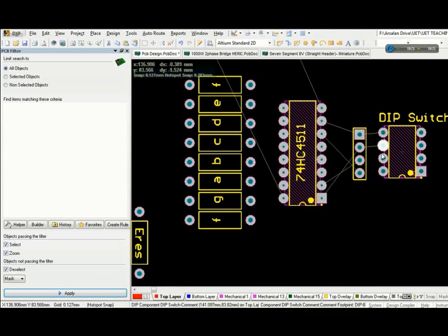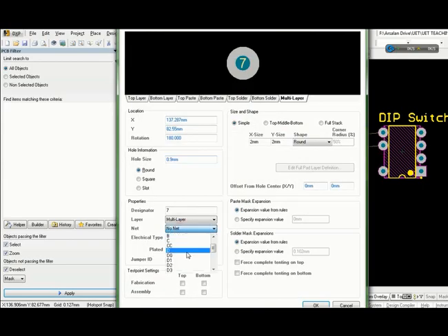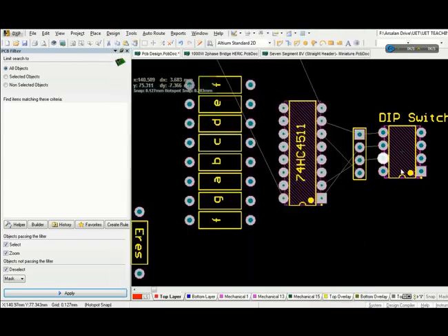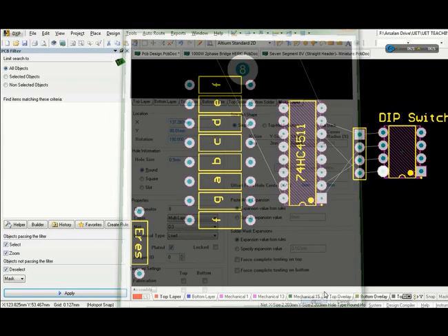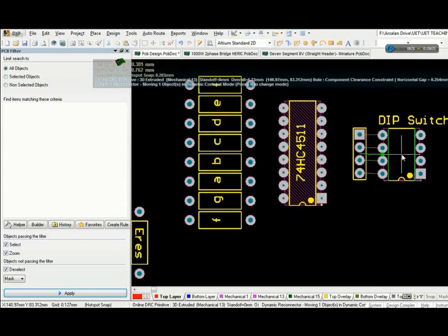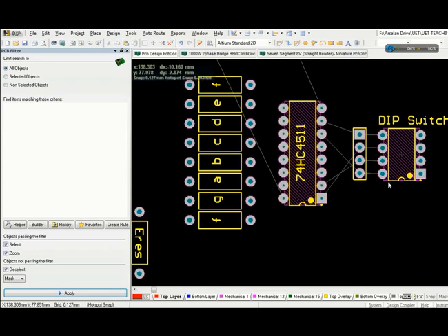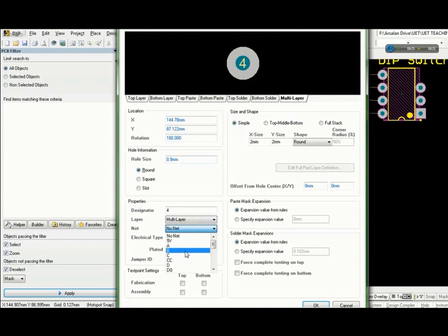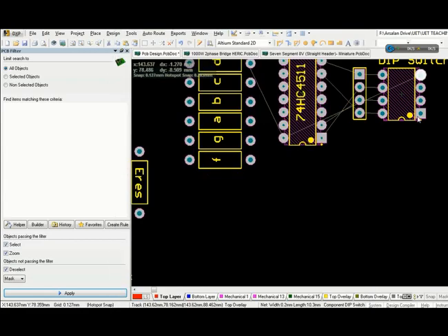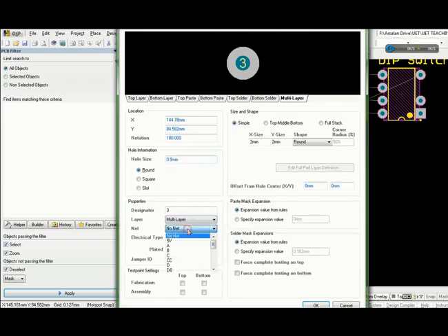So it will be better actually, because when you are controlling it physically, you know the least significant bit is the farthest most point on the left side, or the right side actually, sorry. So you can see this is a dip switch, and all these 4 pins on the other side, this one which I am double clicking, it's going to be connected to 5 volt. One thing very important, this whole PCB has a VCC which is the input voltage, and 5 volt which is the regulator output voltage by which all of this PCB is working.